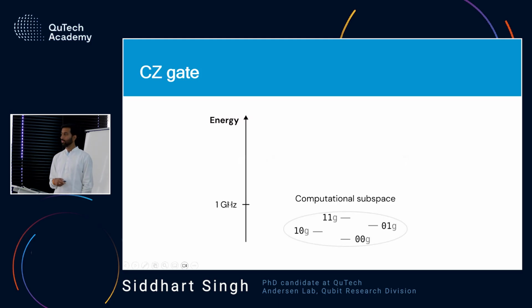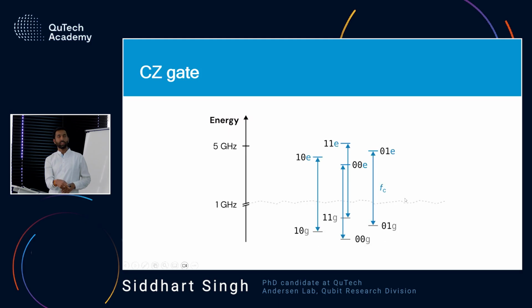And now, if you think about the coupler, it's also within the system, but it's not being used directly for the gate. The states are encoded on the fluxoniums itself. So the coupler is G, which is the ground state. And the excitation of the coupler can go from the ground state to the excited state. So all these 4 levels have, let's say, the same transition of the coupler from ground to excited state.